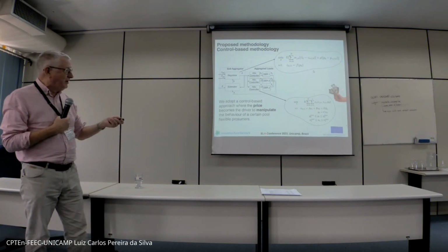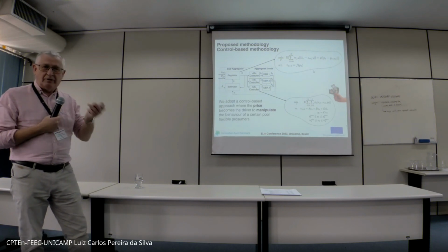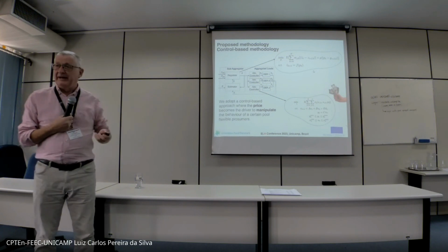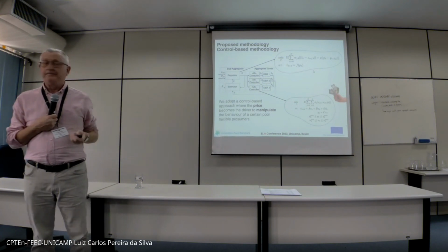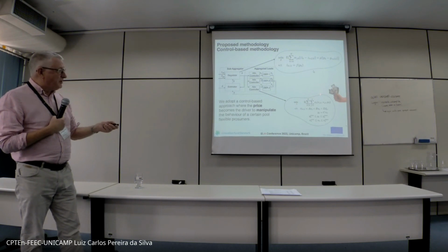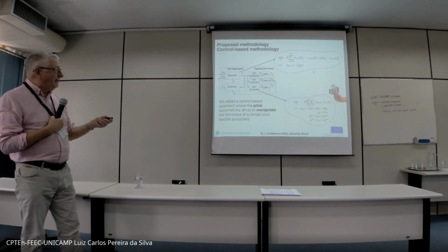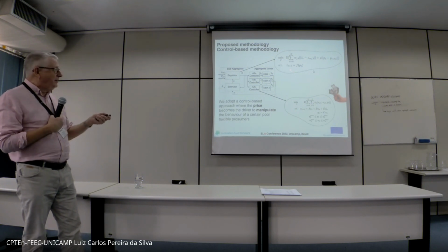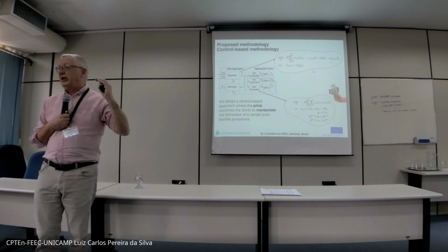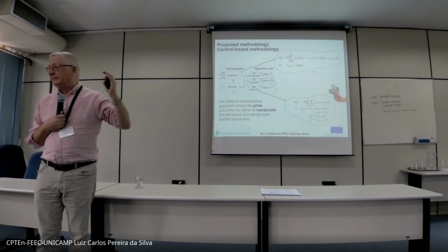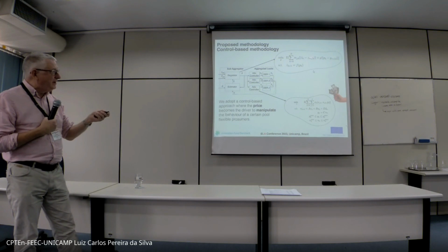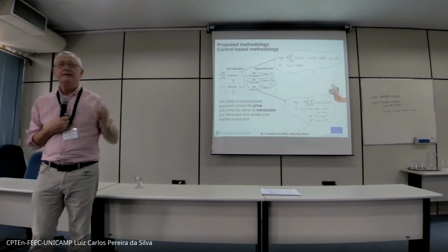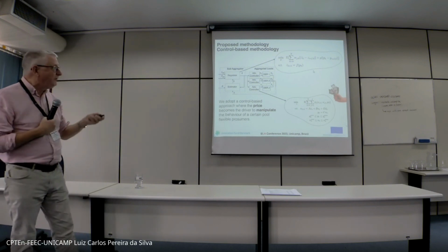Here a building owner will probably try to lower the cost. So he's typically using a controller, which could be an economic MPC type of controller, and it looks like this. He responds to the price, and on the higher level, the DSO or whatever we have here would probably try to do some peak shaving or voltage control. He might have some reference load which he would like to follow or be below, or a reference voltage, so it could be many different things.